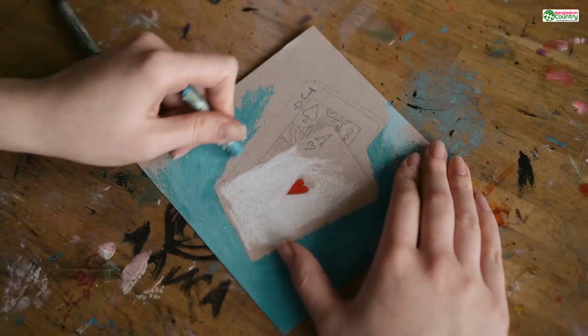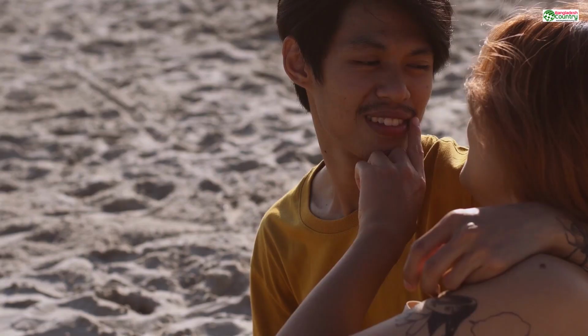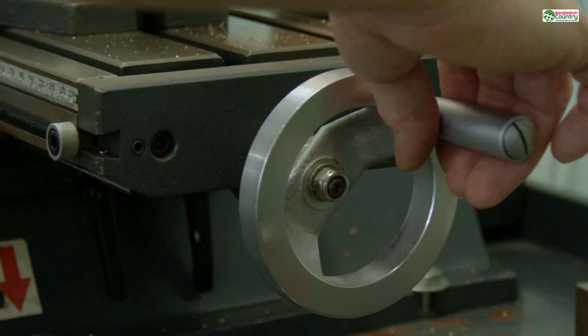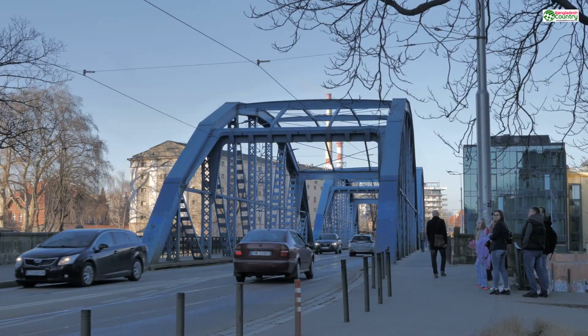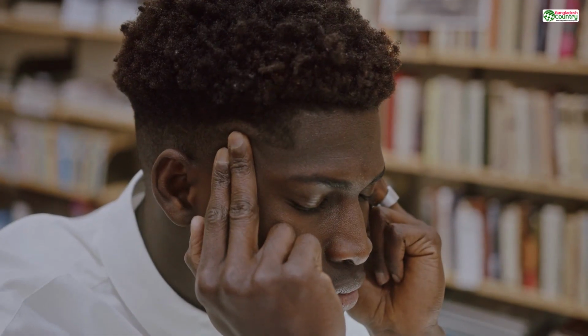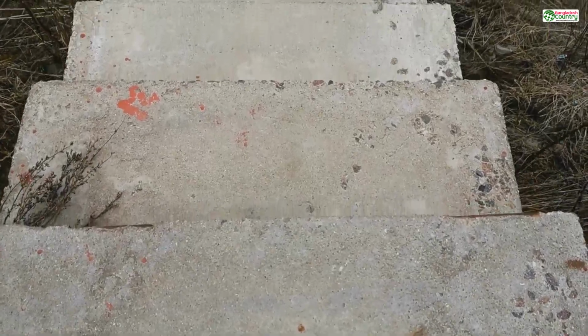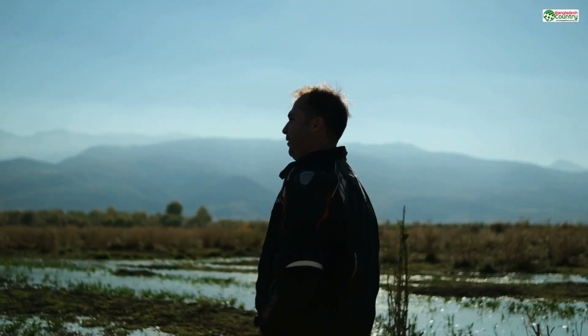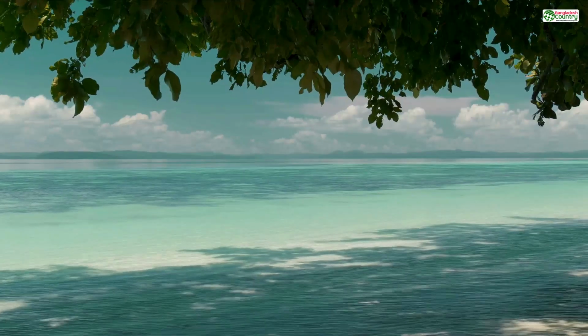It can handle a little bit of an angle because most of a new layer is still resting on the layer below it. Think of it like a staircase. Each step juts out a little bit, but it's still mostly supported by the solid mass beneath it. This leads us to the most fundamental rule of thumb in 3D printing, the 45-degree rule.